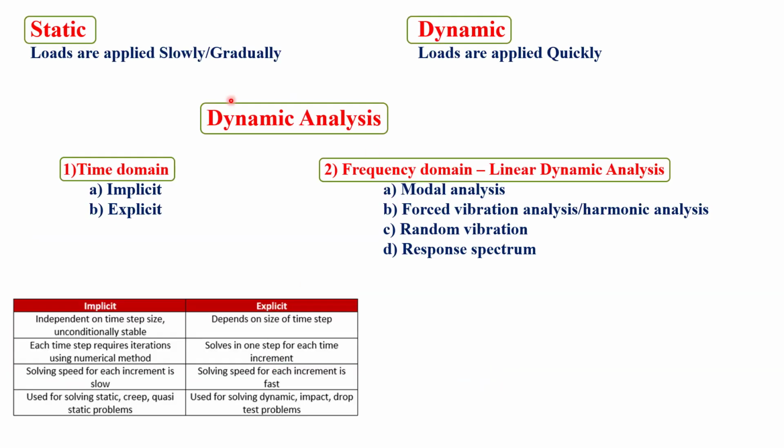Now, these are the types of analysis depending upon the time domain and the frequency domain. When it comes to static, we apply the loads gradually with respect to time. In dynamic, they are applied quickly. In the dynamic analysis, we have two: time domain and frequency domain. In the time domain, we have implicit and explicit. You could see the details here. One is completely independent of the time step size, while here it depends on the time step.